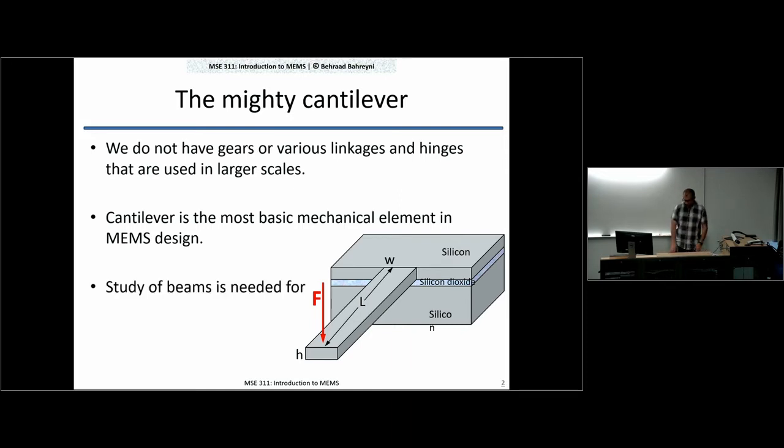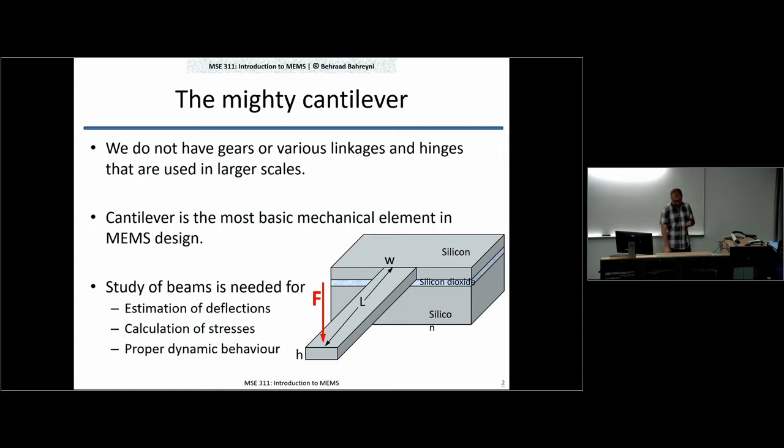And we need beams for almost everything in MEMS. We need to study beam responses in a lot of cases. A beam is used as a spring in MEMS applications, so you want to know its deflections and its response to forces. Beams are used to apply stresses and strains and as connections between different parts of a system. You need to figure out the stress-strain relationships inside these beams.